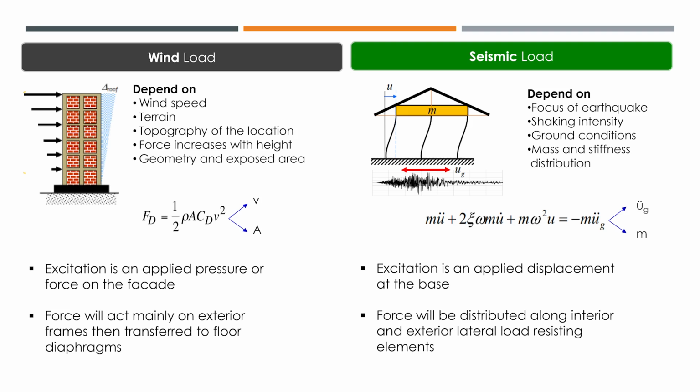So that's why both of these designs, for wind and earthquake, require an understanding of dynamics and understanding of the interaction between force and displacement and acceleration and rigidity and all of that. So that's the basis. But the two are opposite. The problem is that if you try to solve the wind, it will make the structure bad for earthquake. And if you try to solve the earthquake, it will make it bad for the wind, because the reason is this.